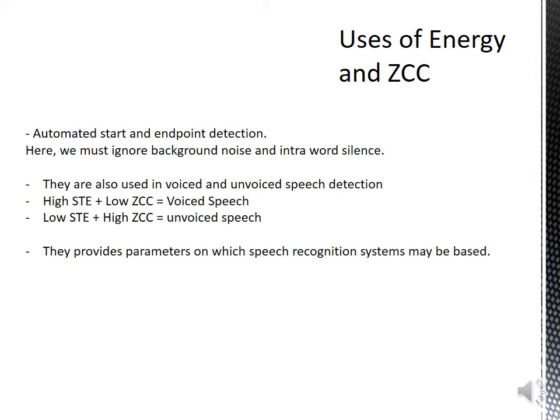They are used in voiced and unvoiced speech detection. If we have a high zero crossing count and a low short-term energy, usually that is unvoiced speech. Unvoiced speech has small energies. Voiced speech, on the other hand, has high energies but a low zero crossing count.